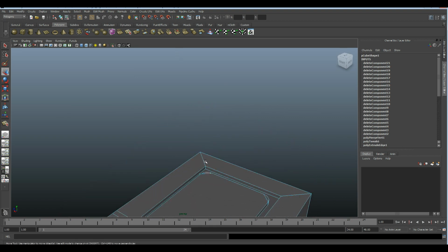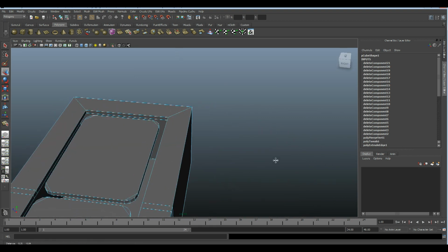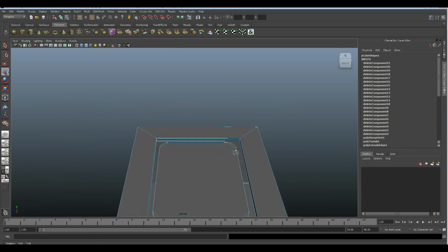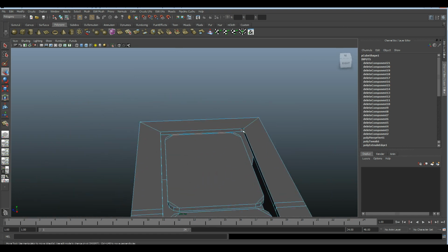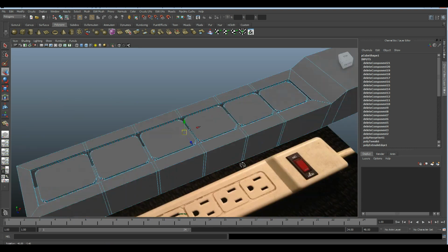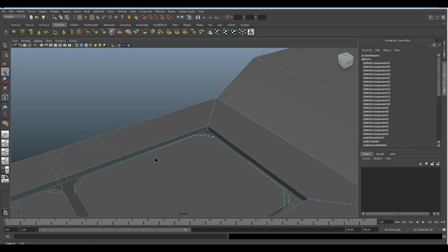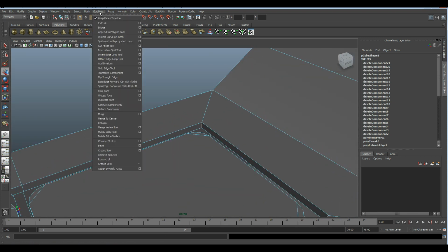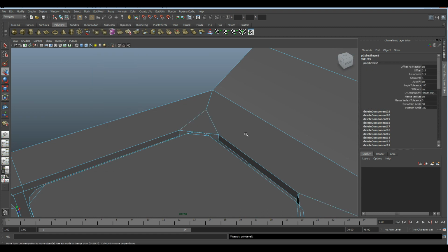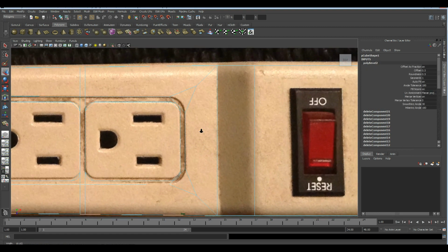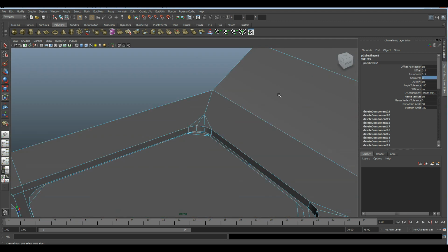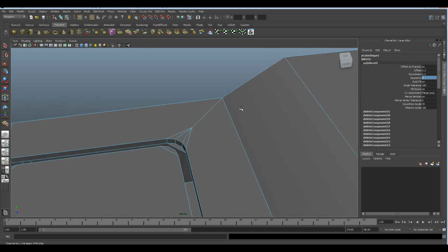Okay. Select that edge. And then I'm going to grab that edge right in there. And I'm going to take a close look over here. And I'm going to hit the Edit Mesh button up here and go down to Bevel. And then go into Top View. And I'm going to adjust the offset here. 0.3. Number of segments, let's change that to about 3.